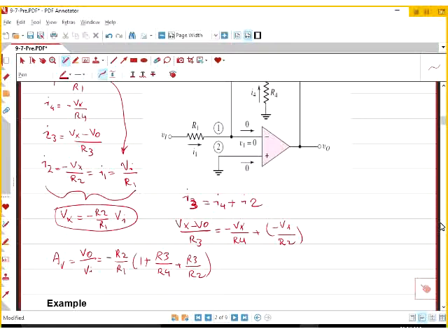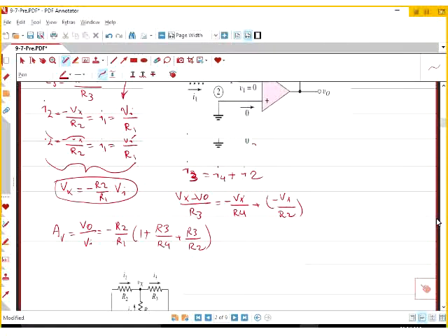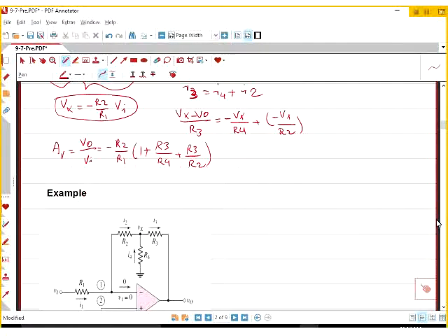Resistors over 500K start to generate noise in the circuit. If you have a bunch of them, then the circuit is noisy. What is the solution? The solution is the T network. You are adding 2 resistors into it. You're going to get a little bit more complicated equation, right? Let's give one example and see how it works.